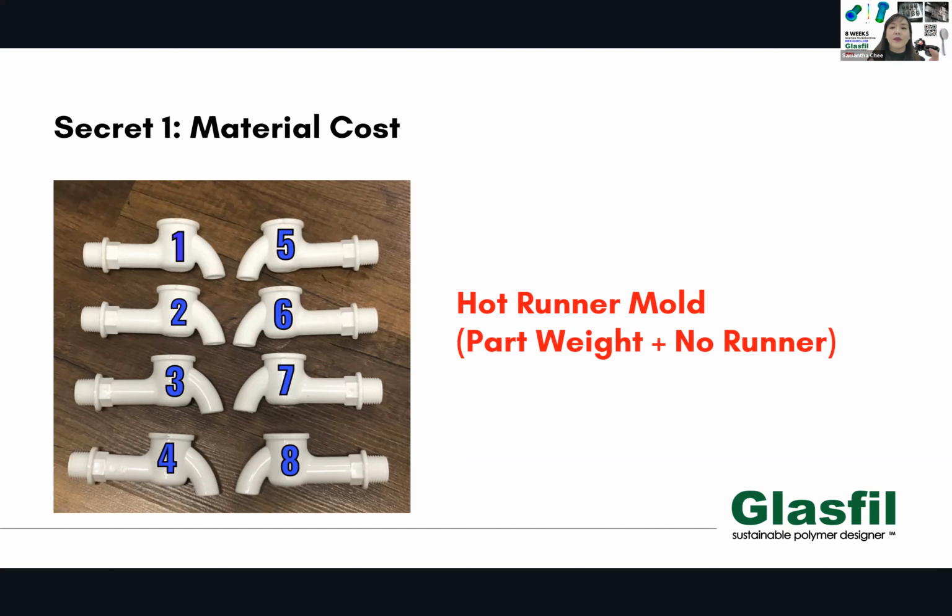And the cons, meaning the disadvantage about a hot runner mold, is it requires a little bit of maintenance from the people running it. Secondly, you will need more cost to produce this mold because each and every one is a hot runner. So you probably spend an additional few $100s in US terms, or a few thousand in Malaysian ringgit, to have this additional system.